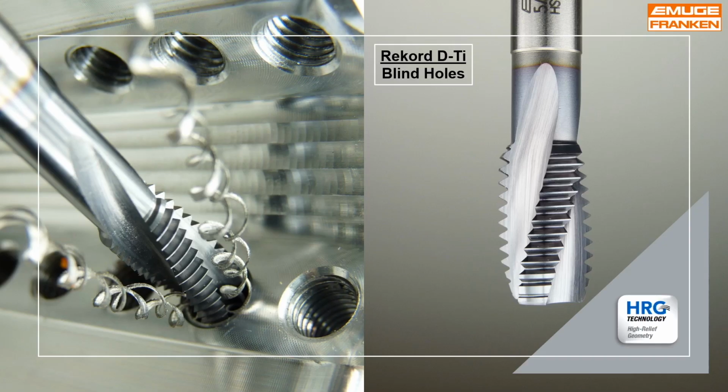The cutting tap program consists of two primary designs, one for blind holes and one for through holes that have been specially engineered for titanium. Here we see the blind hole design, which incorporates a 15-degree right-hand flute angle for optimized chip evacuation in the reverse direction, semi-bottoming chamfer, ground with HRG technology and TiCN coated. More in a moment regarding HRG technology.